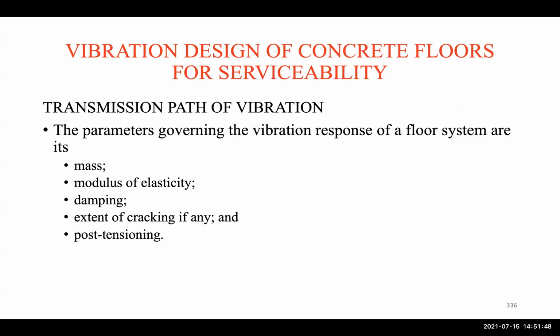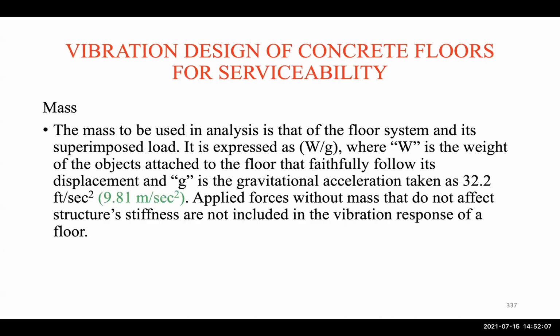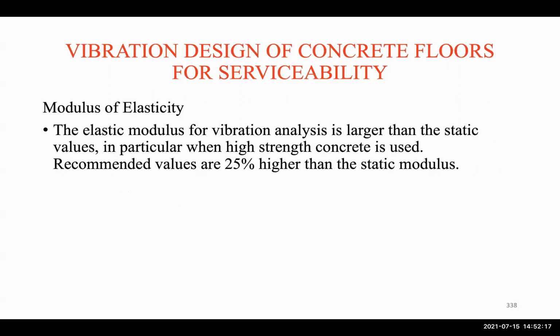So the parameters governing the vibration response are the mass, modulus of elasticity, damping, and extent of cracking, if any. Luckily we will not have that in PT floors, but in some parts of the world, according to their codes, it will become a parameter, and of course post-tensioning. Okay, the mass is determined as the weight divided by the gravitational acceleration g. So we need to determine that.